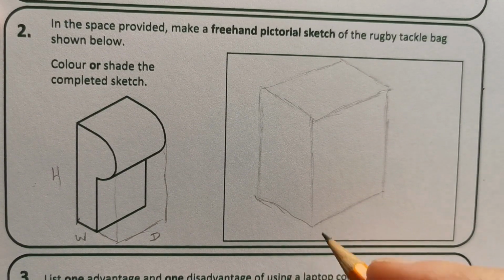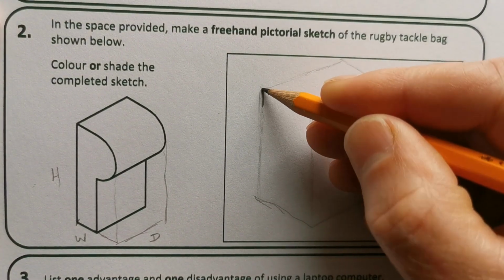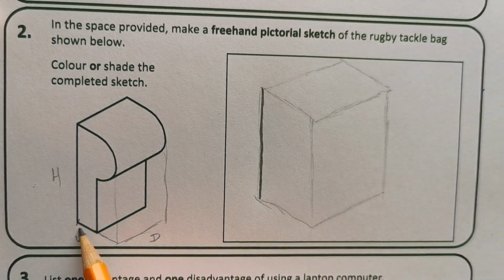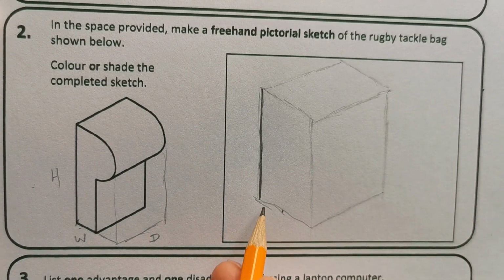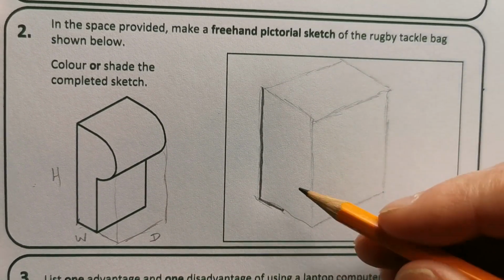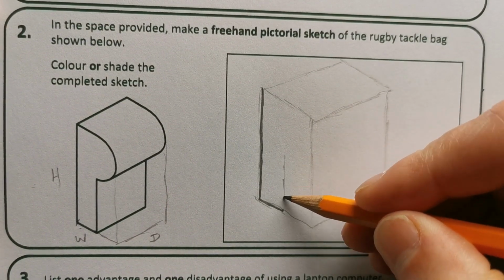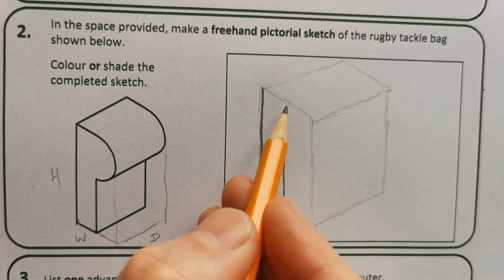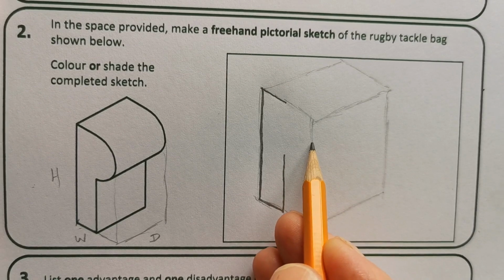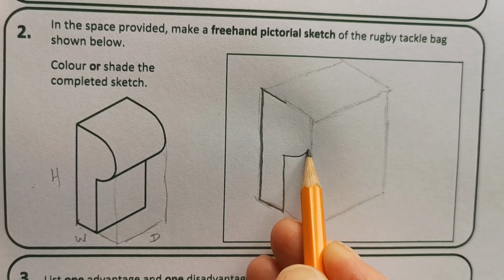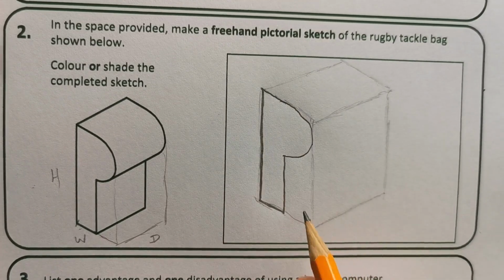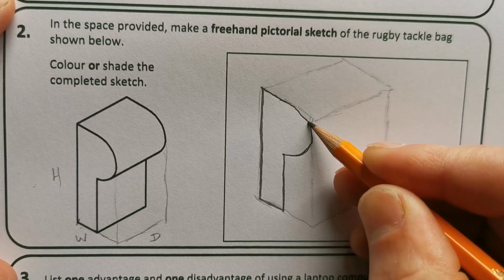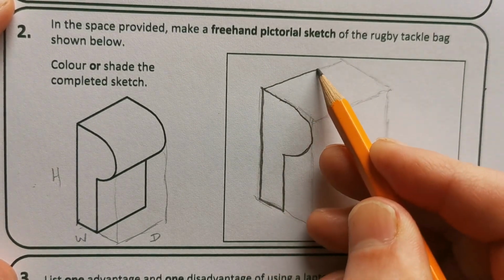Okay, so that's our 3D box that we're going to use now to help us to draw this shape. So that's coming out about halfway here. Then this goes up vertically. I'll just draw the light first and then heavy it in. And then we've got this P shape that should be going to about here. So there's the shape of that there at the end view. So just take that heavy across here.